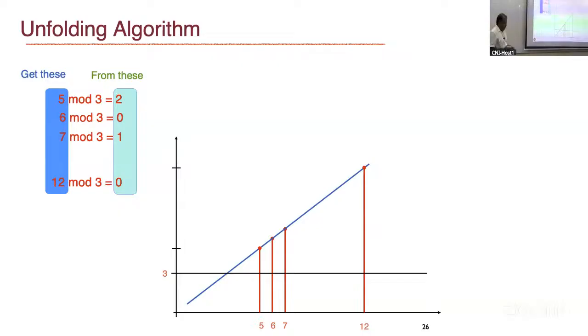Okay, are we able to reconstruct the signal? Yes, no. What were the original values? 5, 6, 7, and you are getting 8, 9, 10. Is it still linear? Okay, just there is an offset. Yes, fine. So here the idea is that if you keep on oversampling, from one sample to another sample the signal is not changing drastically. Agree? So let's say you have some signal like this.